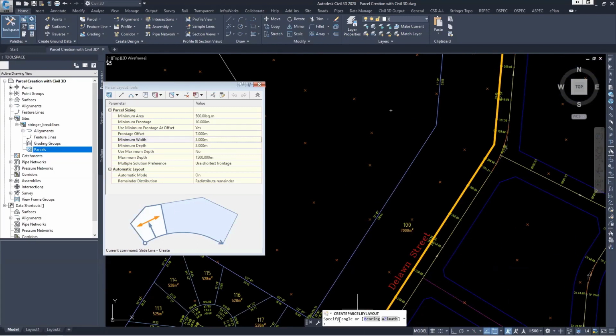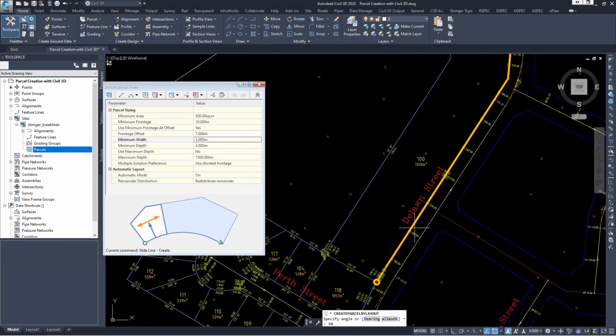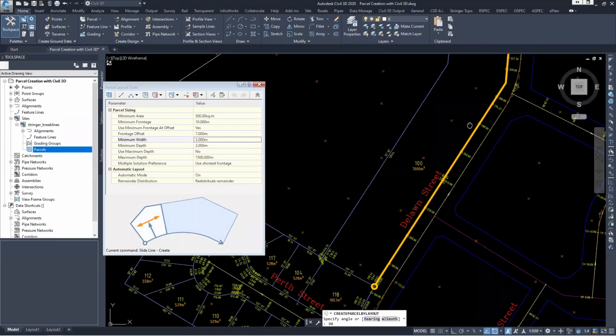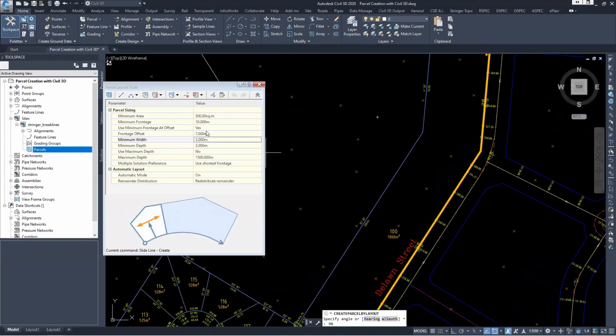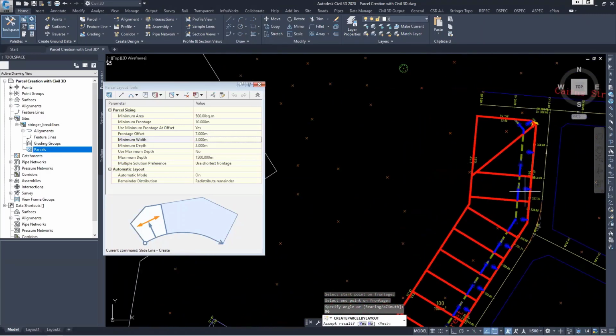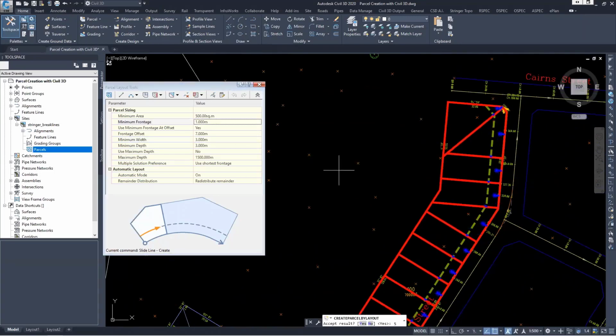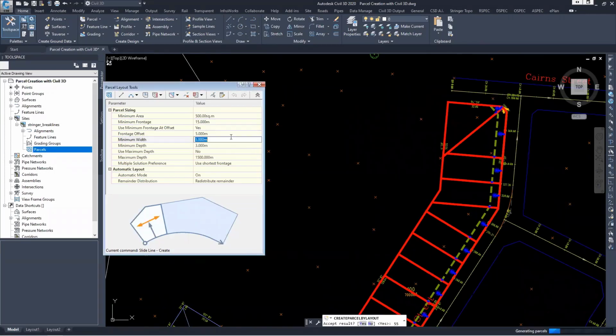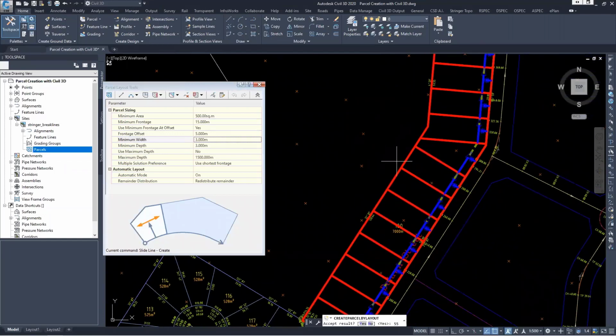So what we actually want to do is specify an angle for it to work on, in this case 90 degrees. So it's going to shift us so that it's working at 90-degree intervals from here, applying our settings. So I'm going to hit enter. It's going to create them, and you see how they're nice section blocks. I might change that to 15 to make that end one a little bit cleaner. Five key's not working for some reason. Make that all a bit nicer.